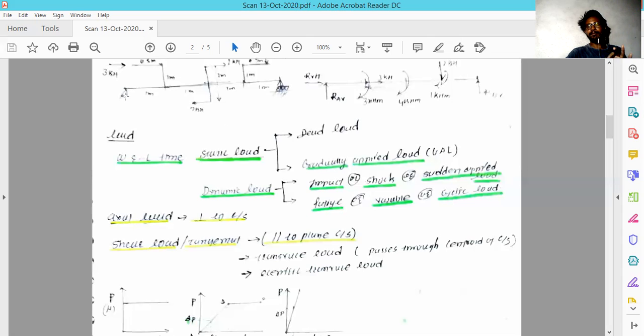At the hinge end, we will get two reactions: one is the horizontal reaction, and the second is the vertical reaction. When you move 1 meter away from this hinge point, you will get one moment, which is in the clockwise direction. That is 3 multiplied by 1, which is 1 meter away from the center of your beam. So 3 kilonewton meter, the torque is going to act at that particular point, and the force acting from left to right is shifted toward the beam.